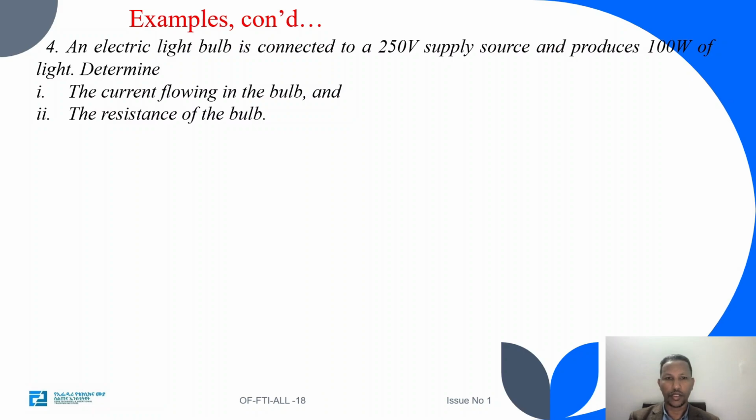In the last session, we have seen one of the basic laws, which is Ohm's law, the relation between voltage and current, the relation between power and voltage, current and resistance, and also the relation between resistance and conductance. What does it mean resistance? What does it mean conductance? How current will be passed through the element when the element is expressed with conductance or when the element is expressed with resistance. And we have seen also the relation between voltage, current, and resistance using Ohm's law.